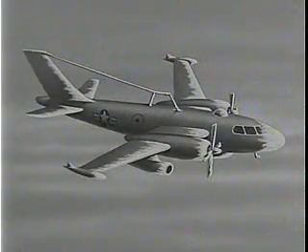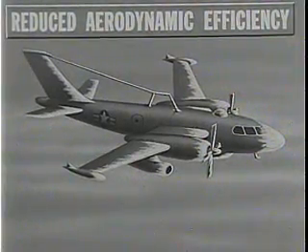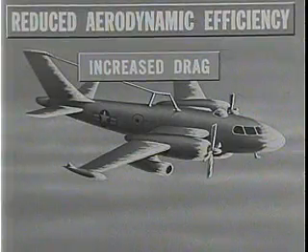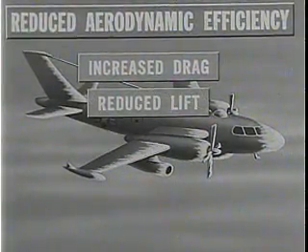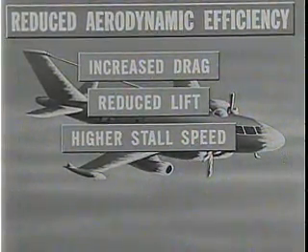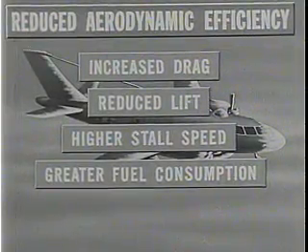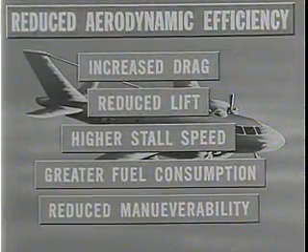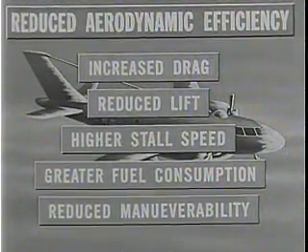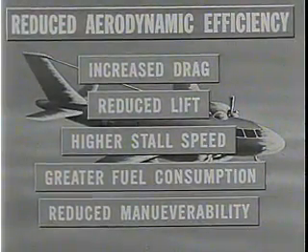In general, it is important to remember that ice reduces the overall aerodynamic efficiency of the aircraft. It increases drag, reduces lift. Stall speed is higher than normal. Fuel consumption is greater. And above all, remember that maneuverability is greatly reduced. Avoid steep turns and fast climbs. And when landing, maintain the power needed to ensure sufficient airspeed to avoid stalling.